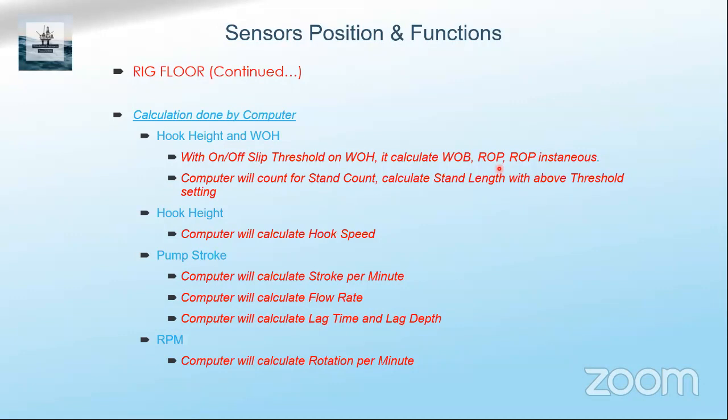There is no sensor called ROP. Okay, it's a calculator. Then similarly, like stand counts, when we are tripping, sometimes what is a stand? It's a one drill pipe single. In most cases, there are three single pipes, okay, the three singles join together and are called a stand. In some places, in small rigs, it's two.